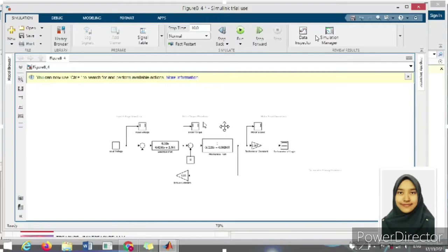Now let's take a look at activity 2 number 2, where we need to repeat step 1 in activity 1. We need to set the input voltage to the value obtained in step 1, activity 2, and then set the brake to the parameters given, which are 0, 3, 6, 9, 12, 15, 18, and 21. After we set the brake scale, we can run the simulation and read the motor speed value.